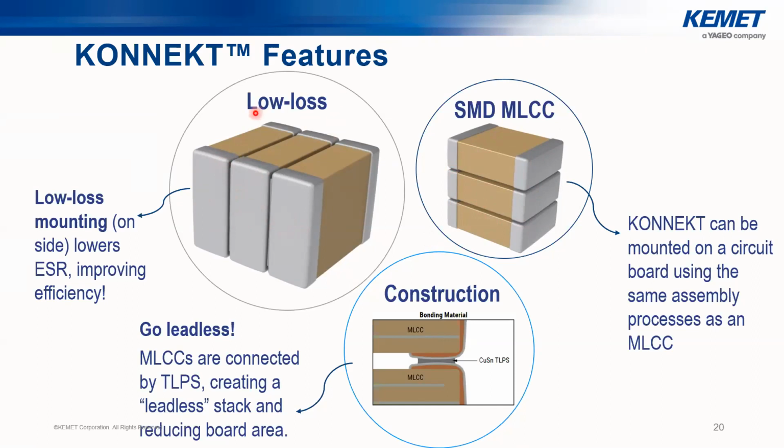And why is it called low loss? It is really related to the ESR of the capacitor, since the connections inside the capacitor are directly connected to the circuit. There is no need to go to the first capacitor, then to the next, and then to the next, which will induce additional losses in the circuit and increase ESR. So we have the capability of proposing these two types of connections.